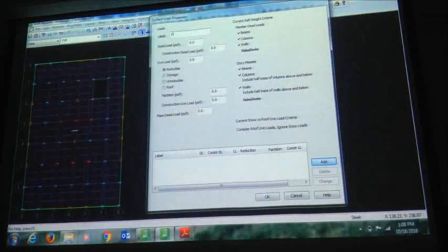So let's give a surface load, and I'm saying that that's floor load. Dead load, remember what was the weight of the slab? 145. No, that's for concrete slab. 75. 75 PSF, right? In our class. How did I get that number actually?